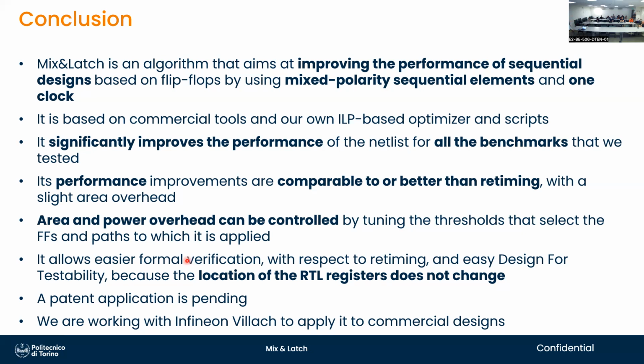So if you find yourself changing how you approach RTL and being more comfortable with perhaps having less combinational logic between flip-flops, because you know that it's going to be optimized even further once doing mixed flip-flops and latches, sure, that would speed up the design cycle.